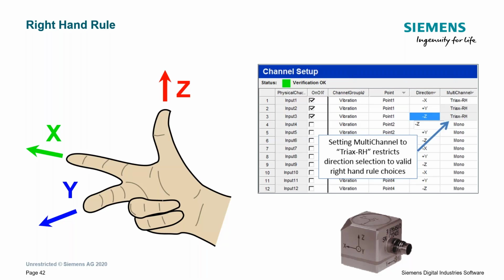If I have to put, say, that accelerometer in the negative X direction, it'll account and say, okay, that means the Z is -2. And the nice thing about that is I don't have to go through and correct my directions of my accelerometers after the fact to make sure the phase is correct when I look at these mode shapes. It's nice to have something that's looking out for me going into the test as well. So that helps with that test setup and execution.